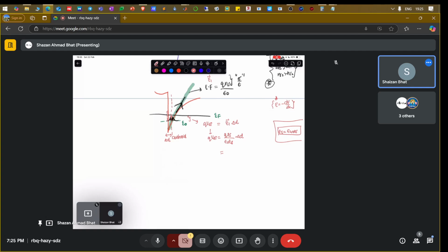And what are the things we have computed from it? We have computed VDI earlier, as a function of NS, which was something like this, using the Fermi-Dirac integral. Now you can write VDI in terms of this particular equation, and then you have to obtain this delta D, the distance of the centroid. When you do it, you basically have to rearrange. You get delta D to be equivalent to pi h bar square over m star epsilon naught epsilon s.